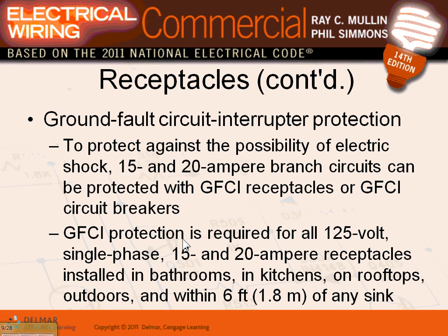GFCI in a commercial building, guys. Now we're talking commercial. A review of GFCI in a commercial building: every receptacle within 6 feet of a commercial sink, with some exceptions in hospitals, must be GFCI. Outdoor receptacle, GFCI. Indoor wet location receptacle, GFCI. Bathroom receptacle, GFCI. Kitchen receptacles, GFCI. What else have we forgotten? Rooftop receptacles. Any wet location has to be GFCI.